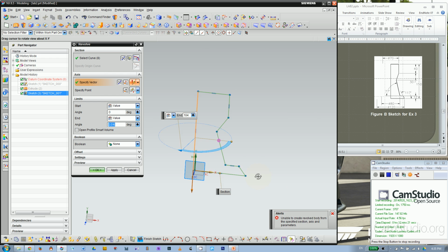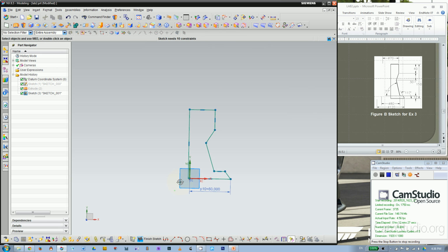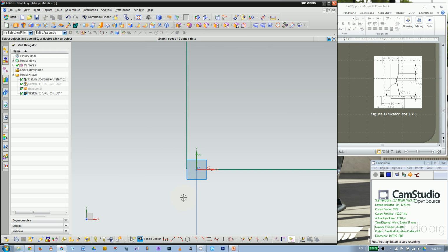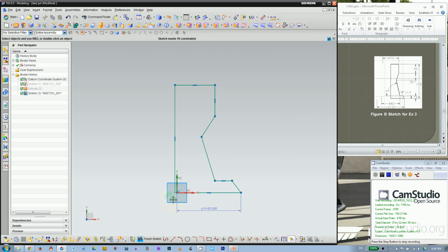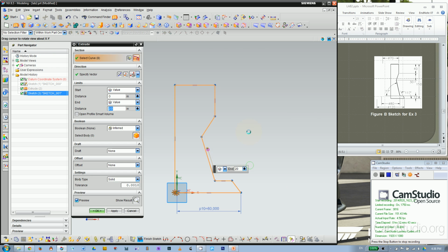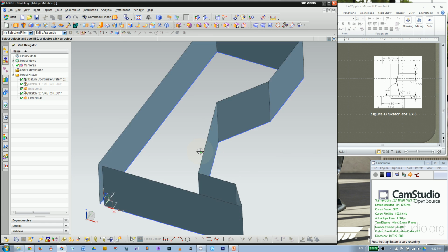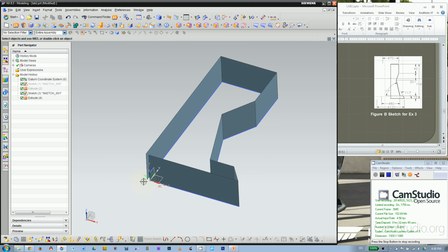Okay, it's not doing anything now. Okay, then cancel. So the point is, most of the time you want the sketch to be a closed loop. This is open loop. Okay, it's not closed. And maybe you can extrude this sketch, but we would say, okay, why does my sketch look like this? Because it's not closed.